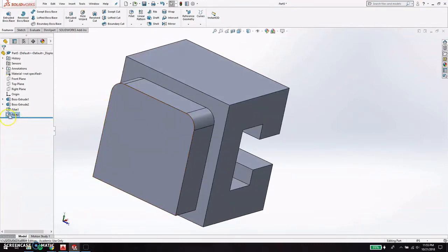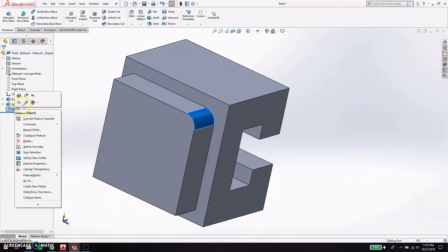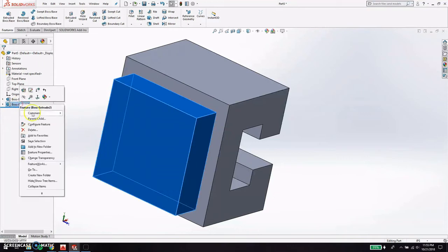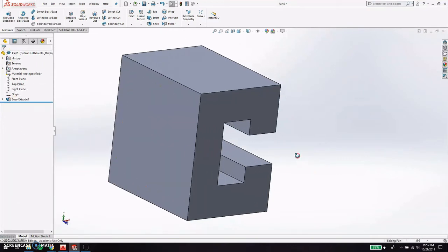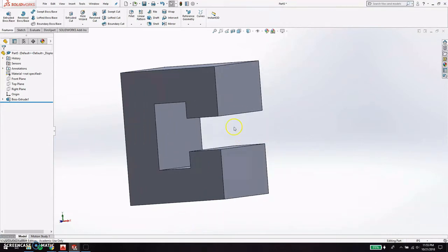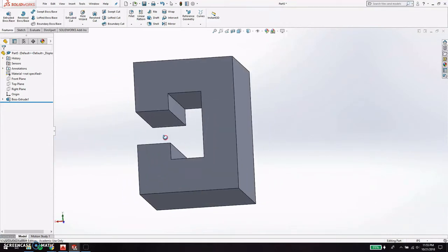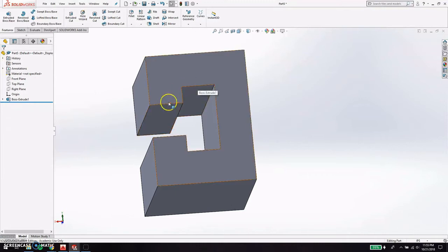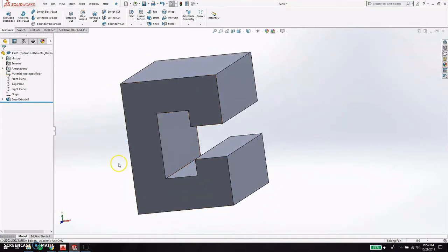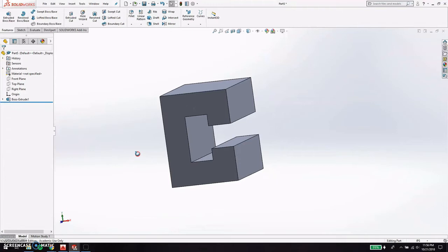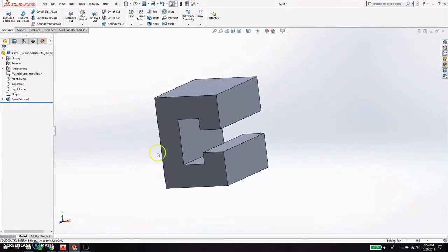Yeah, so I said I'm not going to keep this, so I'll just go here and delete everything out. I'll delete this fillet as well, and I'll delete this last boss extrude, and I'll delete this sketch too. And then we're basically back to normal. If you want to add a little backdrop to these guys, it's pretty easy. You just have to make a little sketch the size of this little slotted area and then extrude that by however long you want it. Pretty easy. I'm not going to go to that level of detail for this tutorial, but with all the stuff that you learn here, it should be pretty straightforward how to do that.